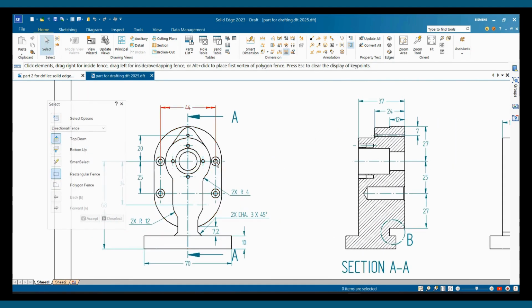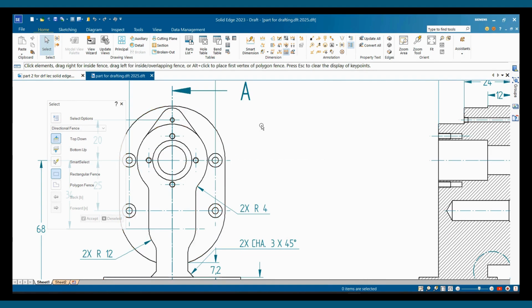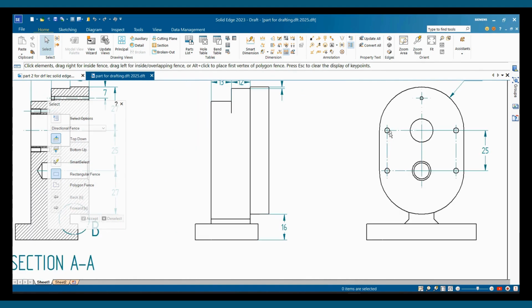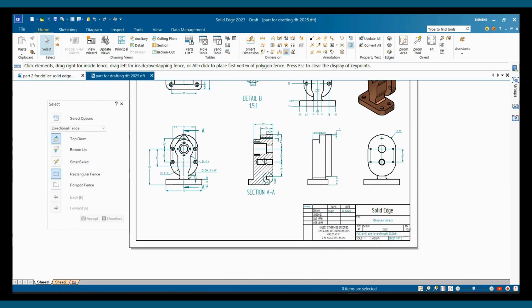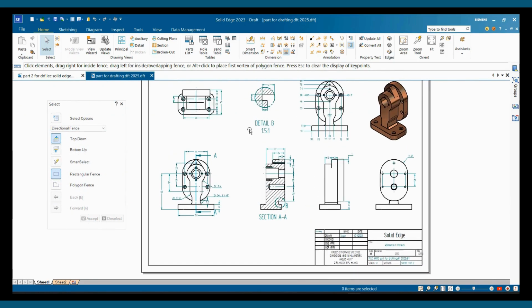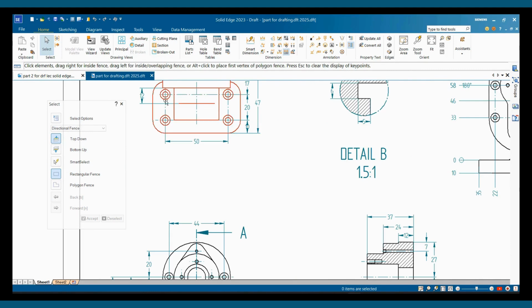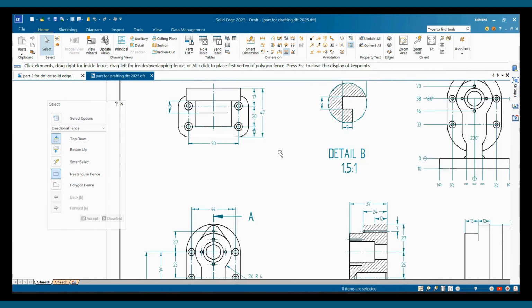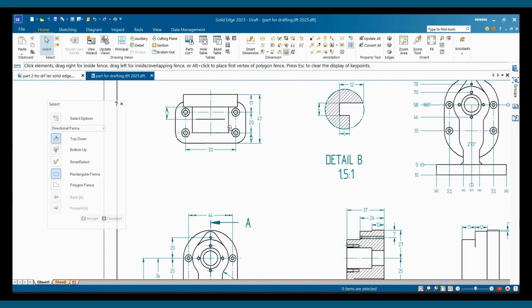Here we have the countersunk holes that we have provided. We have also provided some tap holes here, and we have also seen counter bore holes here. You can see at this bottom plate we have counter bore holes. So we'll apply this callout for each hole now. Select this option, that is callout.